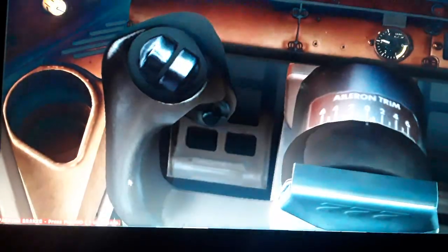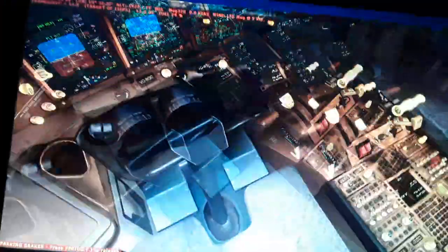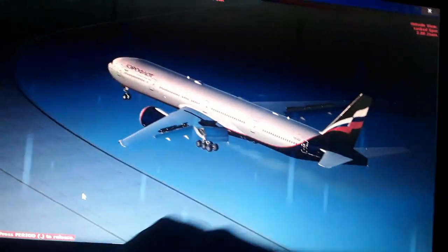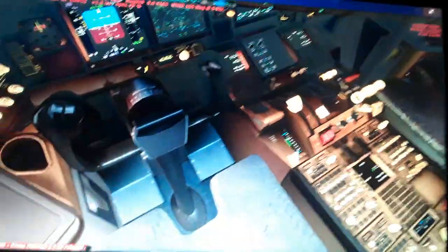So you set the horizontal trim position, pitch trim up and pitch trim down. The horizontal tail, you can use the pitch trim, the normal and the alternate tabs. You can see where the horizontal trim position is. The green band is for flying and for takeoff, and we have it 4.25 degrees. Also, besides having the manual trim order, this is the manual trim of the horizontal tail. Over here, as I told you, horizontal tail that would trim up and down.